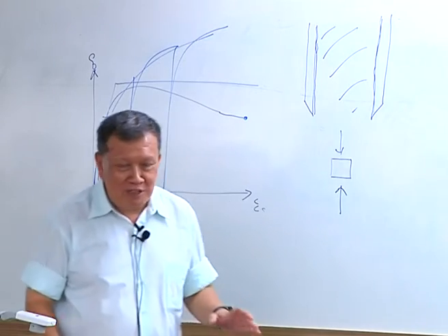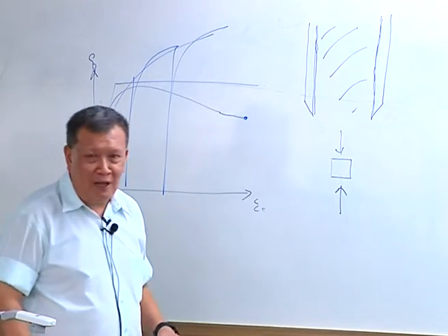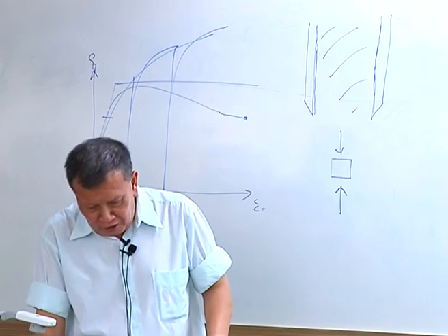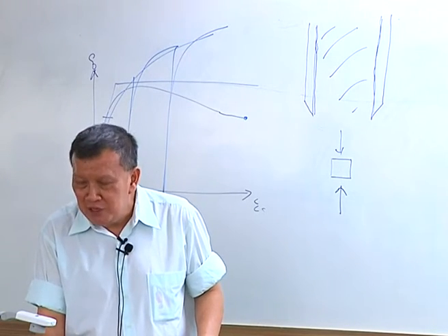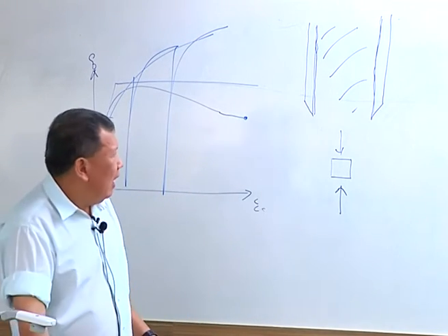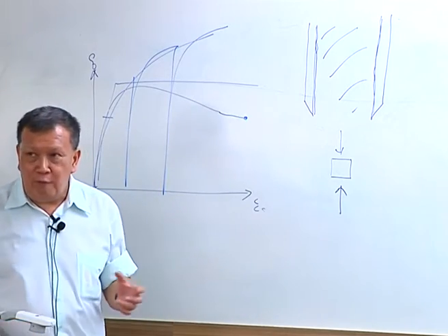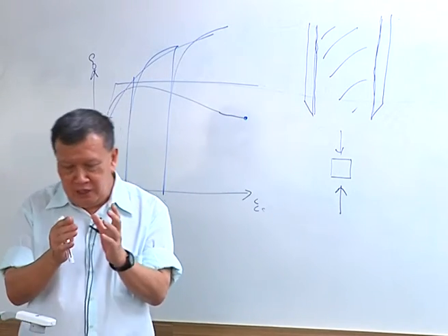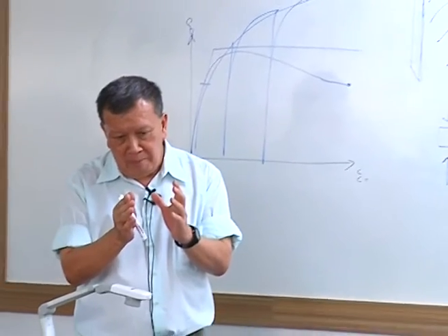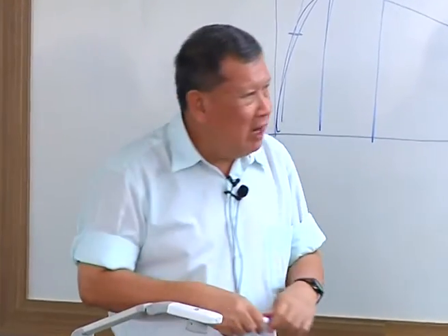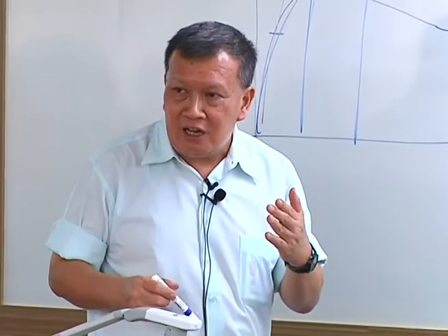That's the way. So most sampling tubes, including the Shelby tube, the classic standard, have this major problem, okay? And of course, there are ways you can mitigate this effect. One of the ways is what they call an inner clearance.